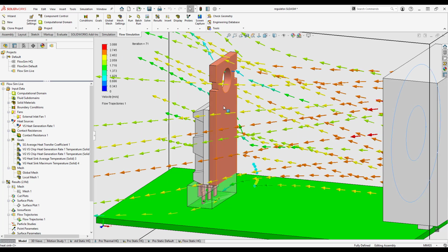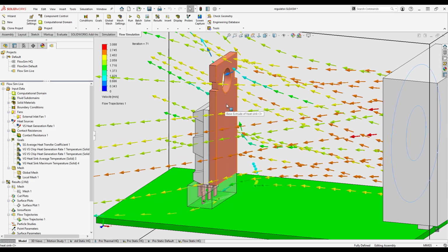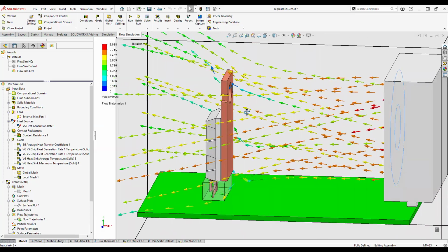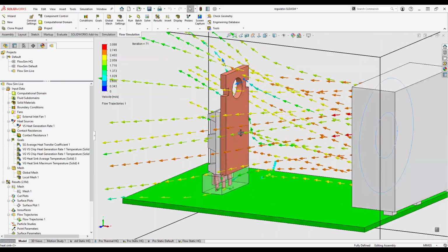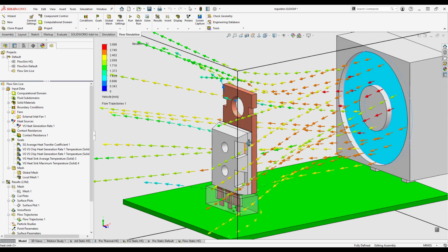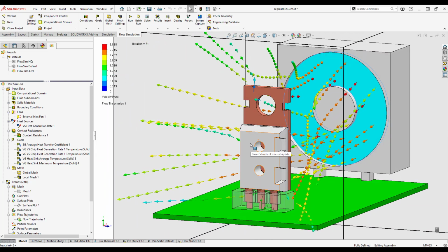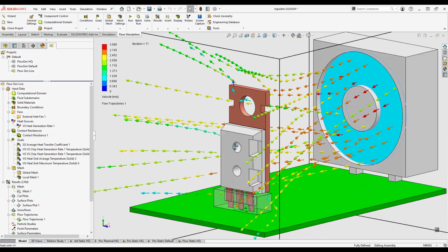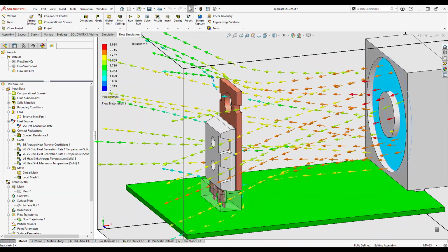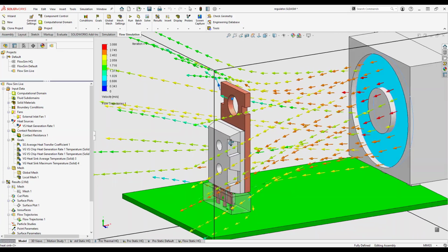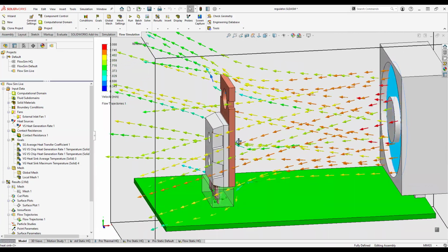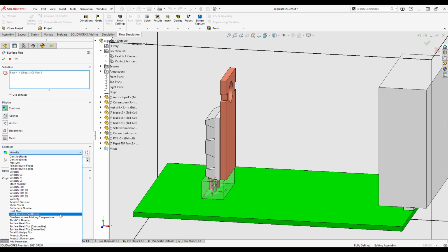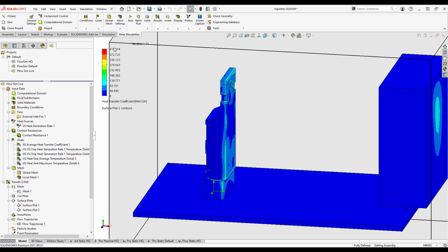So that's why the heat sink was so critical for us to not have to guess that heat transfer coefficient, because there's so much air hitting that body. Whereas on the backside, the guesses of the convection values on the chip being on the other side, that guess isn't as critical because it's not transferring as much heat through convection, since it's not getting as much air hitting it. One more important plot to create is the heat transfer coefficient surface plot. And this is the other critical part.